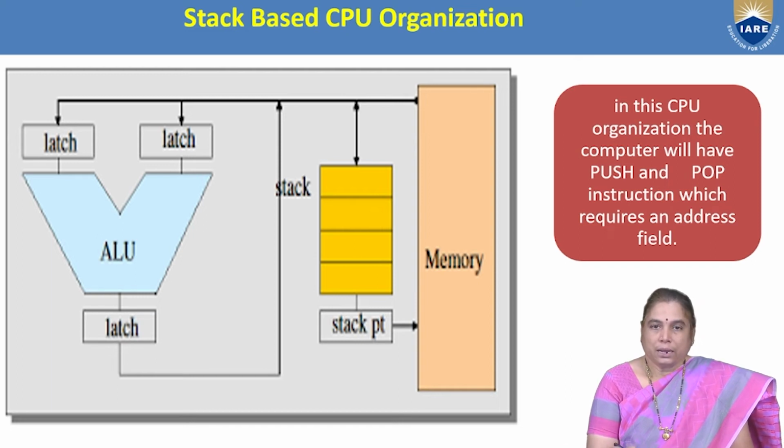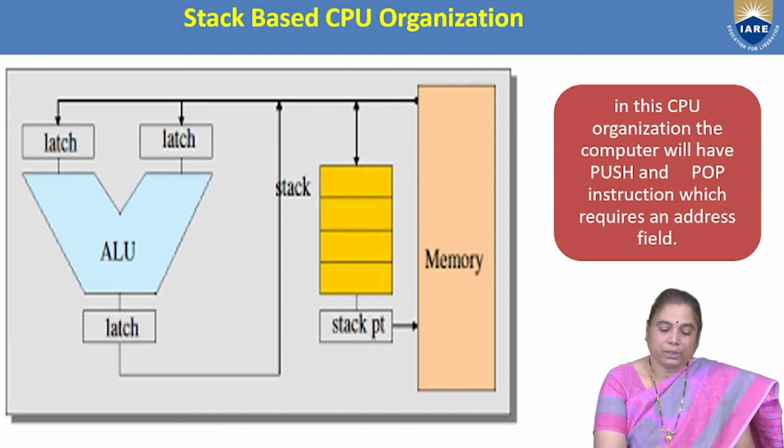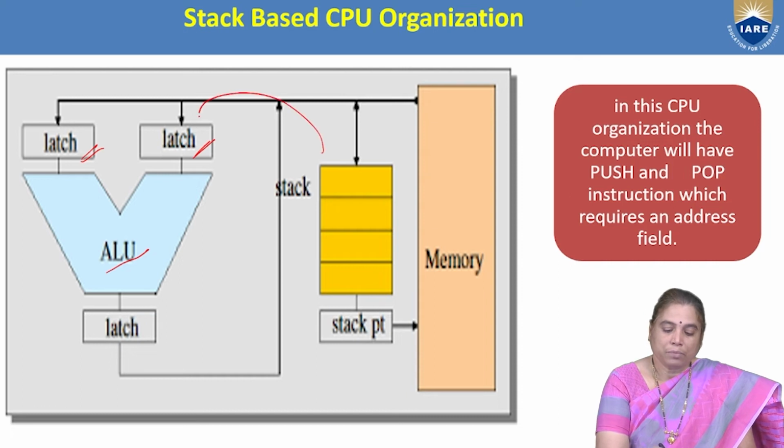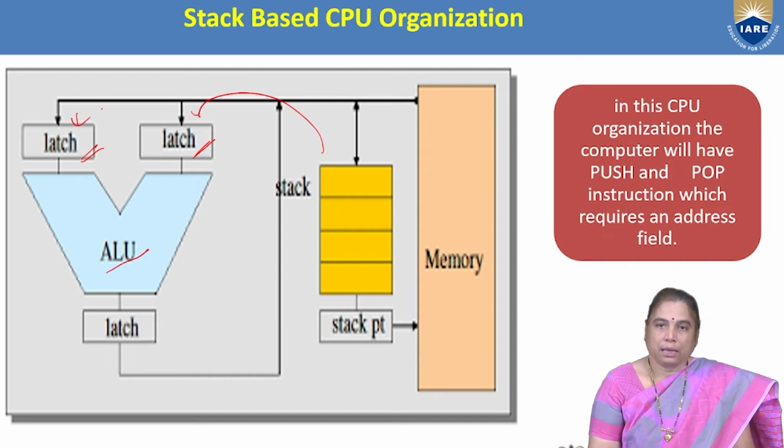To insert data in the stack, the push operation is performed, and to fetch data from the stack, the pop operation is used. The operands can be temporarily fetched into latches to supply the needed operands for the arithmetic and logical operations. The operands are first fetched from the stack and stored in the temporary latches.